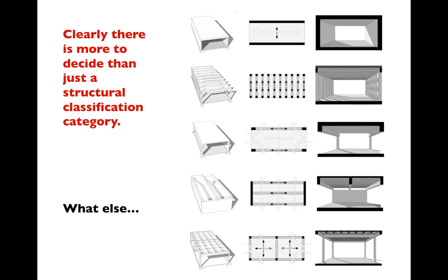We think too about the way that these structures sort of instill architectural or functional patterns to the spaces that we're designing. So even if we're thinking about fairly straightforward section active structures, beams, girders, slabs, we have a number of subtypes where we might be thinking about the spaces that we're trying to put into those floors and whether those spaces can operate on a square pattern, in which case we might put in a 30 foot by 30 foot column grid and expect either a flat slab or a load joist system to fill us in, or whether they need a slightly different pattern.